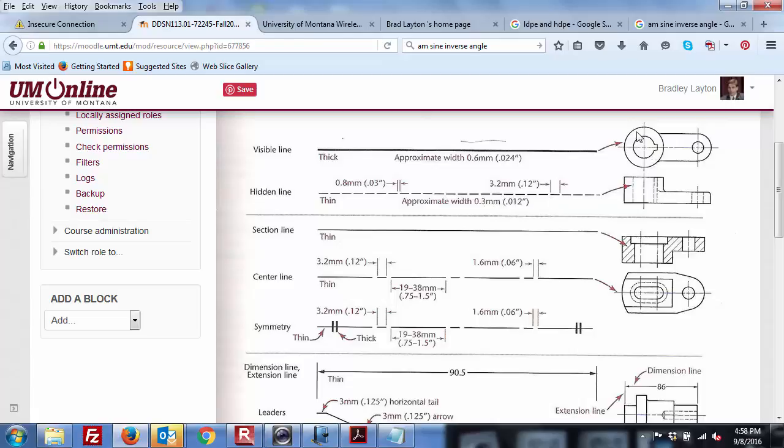Just see, you've got a little part here, keyhole, shaft. The center lines, one thing you should definitely notice about these center lines is that it's dashed, short dashes, then long bars, and the draftsman has actually drawn this in such a way that the top view and the side view line up, and they should. And he's used a single line to connect the two.